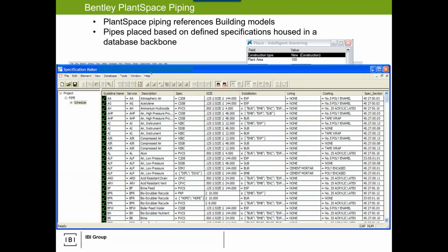This is a spec that I've written, and you know, a lot of them look very similar to this. And again, I'm an architect. I have no clue what's right or wrong, but I can read the standard and impose it on here. Or I did a lot of work with the piping people. So here, for example, if you look, PVC, this AH. So somebody declared that ammonium hydroxide can only go through PVC and not through another pipe. And its minimum size is 0.5. This was an Imperial project, so 0.5 of an inch. Couldn't go down to 0.125, which is an eighth inch.